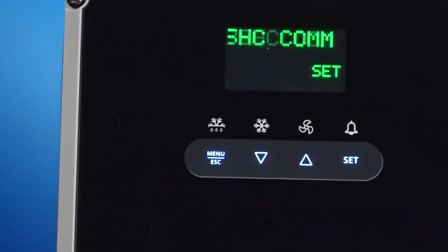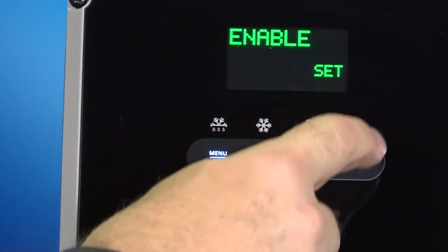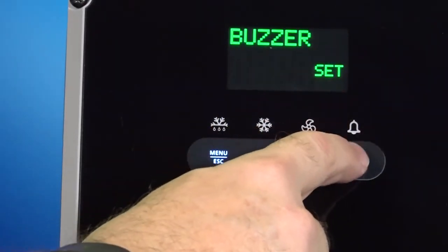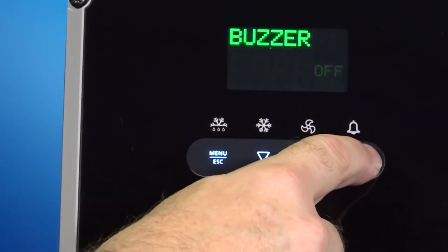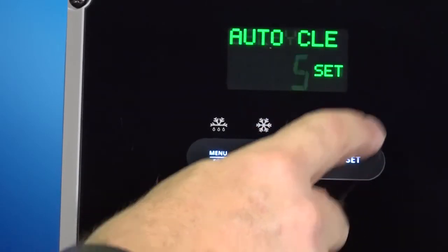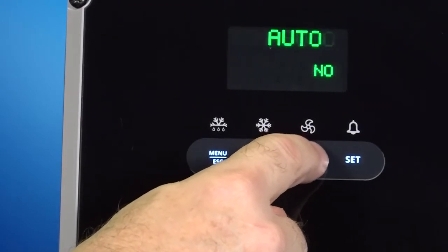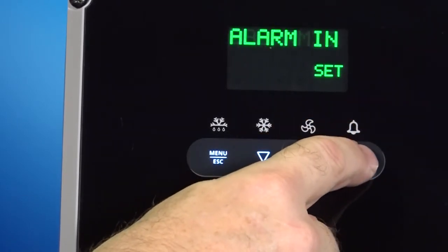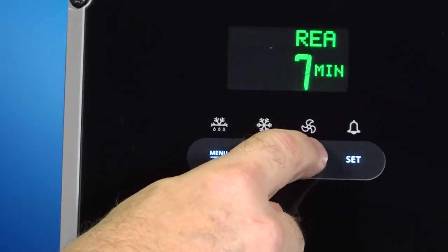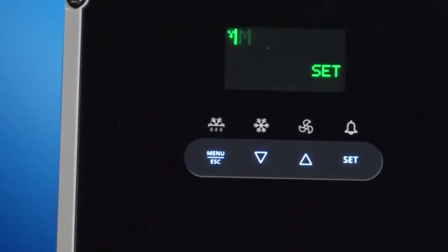The second alarm for the QREV PSHC is for communications loss. The QREV PSHC is a standalone system that, once programmed, will maintain superheat conditions at the desired level. So a loss of communications is not necessarily a reason for concern. It simply means that the Modbus connection between the A525 and PSHC has been interrupted and needs to be investigated to make sure no further issues impact the operation of the system. Again, the alarm parameters are identical to the previous alarm conditions. Simply set the desired parameters.